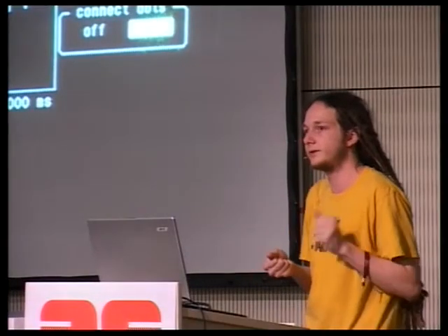Now, looking at a scope, you can see the timing. And once you initialize it, it's waiting for 0x80 to be sent across, because it needs to figure out the timing with which it's going to speak. And then you can view the conversation as bytes going across the wire between the 2 chips.